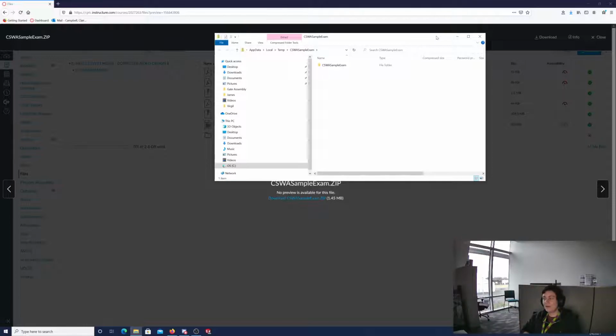I would leave a decent gap. If you have two gears that are interfacing, you would want to make the teeth slightly smaller than the gaps. And you might need to redesign and 3D print things again. You probably will, several times.